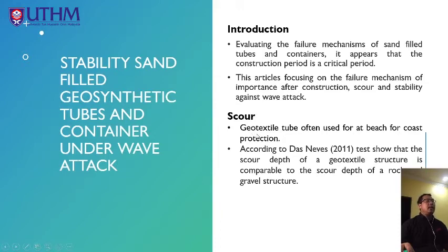You can see geotextile tubes are often used at the beach for coast protection. According to Das Neves, tests show that the scour depth of a geotextile structure is comparable to the scour depth of a rock and gravel structure.